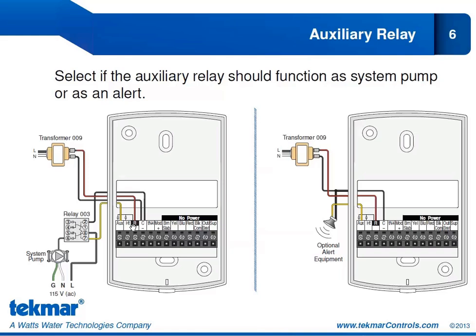And of course, we need line voltage to operate our pumps. So we're going to use the isolation relay, and that in turn will allow the pump to operate on the 120-volt circuit whenever that auxiliary relay closes.